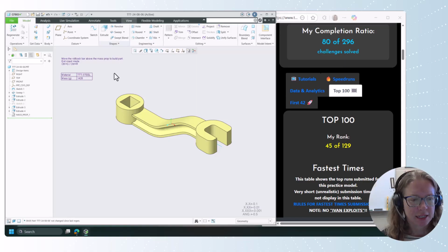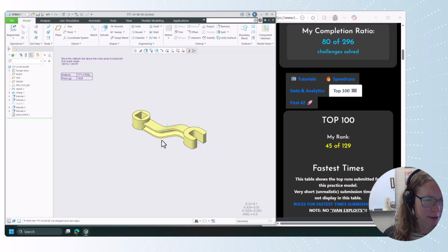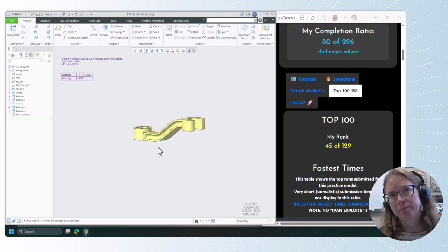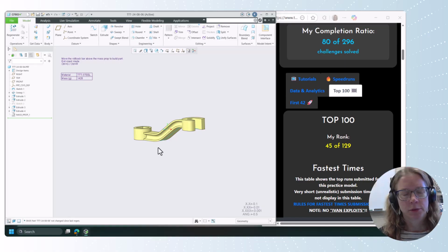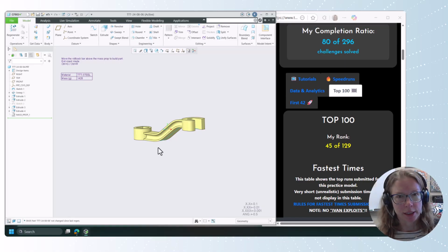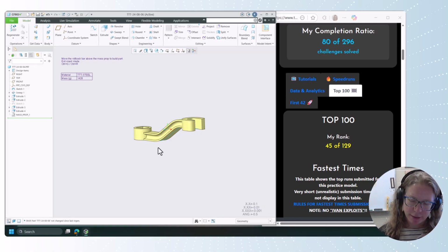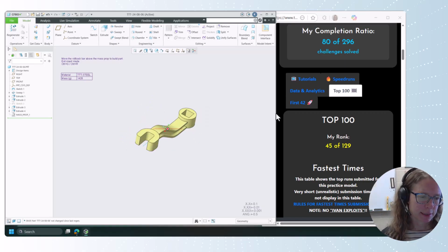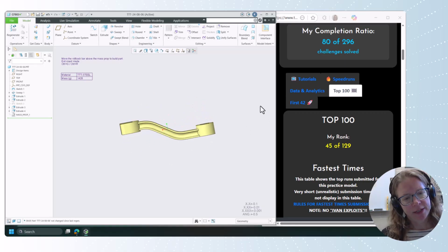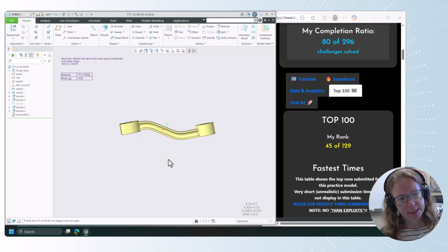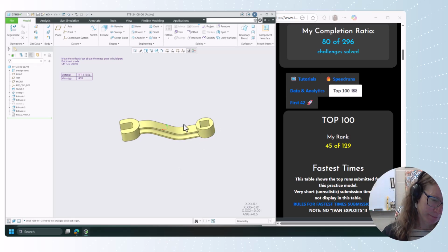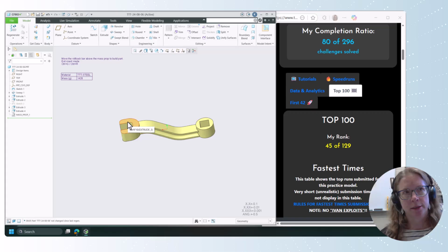When I first looked at it, I thought maybe I'd just be throwing an I-beam on there, but I like the curve. I was wondering if an I-beam could actually work as a starting geometry, and then you'd add the round and the angles to that. I'm not so sure if that saves you anything. You definitely don't want to make the 2 end pieces first, because then the sweep would cut into it and you'd have to redo the geometry.